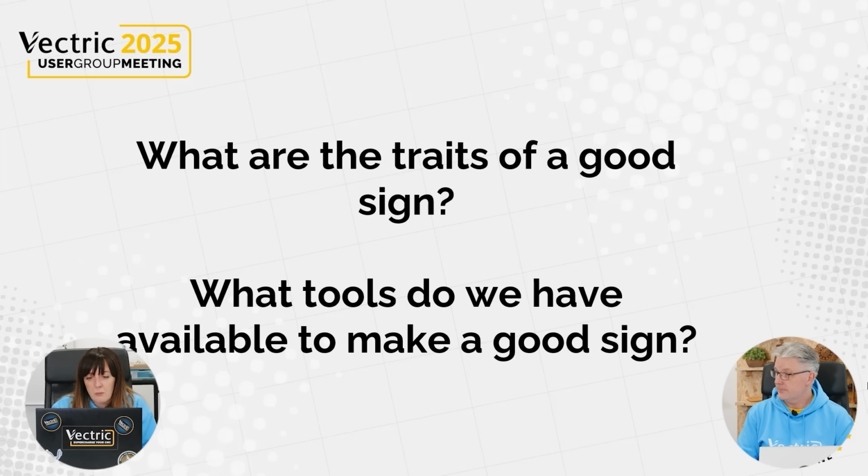That's perfect. The next thing I want to do is draw the larger circle so that we can get an idea of the full profile of the background. So to do that, I want to choose our Draw Circle tool. And I'm just going to draw a random circle in the middle here. Doesn't really matter the size, because now I have the ability to type in the actual radius that I'd like to have.